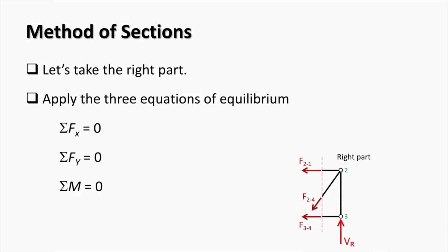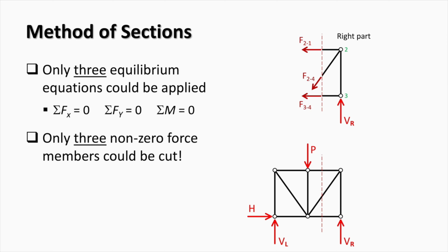Let's consider the problem at hand. We now have a rigid body with forces applied. The system of forces is non-concurrent. Therefore, to find the unknown forces, we will use three equations of equilibrium. We can write only three independent equilibrium equations for a planar problem.